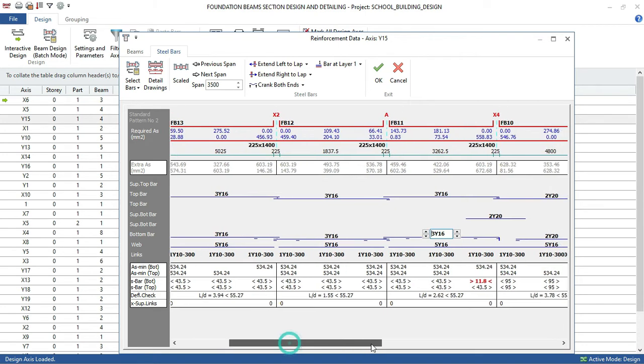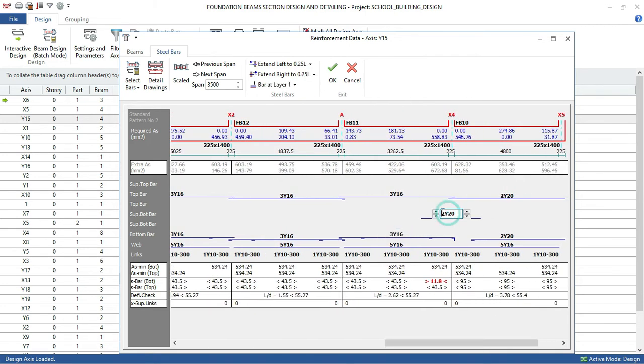Okay, so right now again, I'll go again just now, remove this one entirely, and then come here again. Reduce the bar diameter and increase the number to 3. Now our 3 is still failing, so I'll make it 4. Okay, 3 is okay, but at the bottom here I need to lap it to stop this failure here. So I'll come here right now, lap it here, reduce the diameter of the bar and then increase the number.